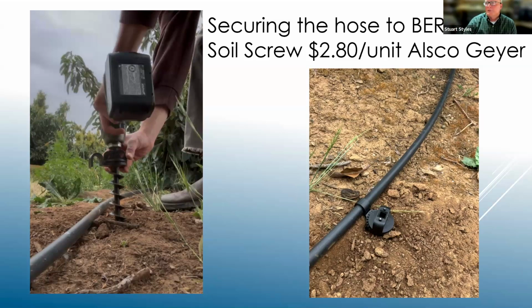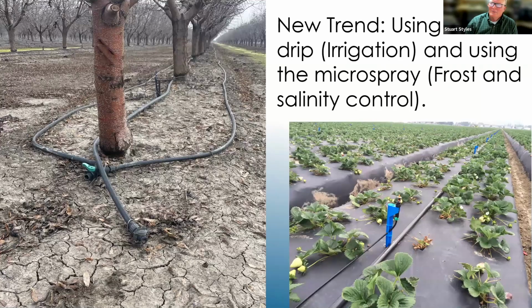So I thought it was at least something to share that was different than the last time I talked about this topic. The last thing I'm going to cover, and I know I'm out of time and want to leave a few minutes for questions, is the trend I see of folks going to dual line, tri-line, and quad line systems. They'll go to a dual line drip, and sometimes they'll have valves on both drip lines. The reason they're valving both of the drip irrigation lines is they'll irrigate one side of the bed first, and then the other side of the bed later.